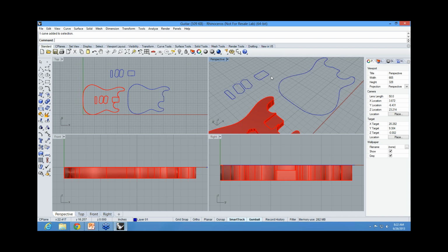And curve Boolean is a great command to, as soon as you make the curves for the TrueType, go through it with curve Boolean, pick inside every letter, and it will clean up the overlaps. It'll clean up the small little loops. It'll clean up that geometry, and you will find that it will work much better for 3D modeling further down the road. And so we use it for finding outlines. We use curve Booleans for inlays, and we use curve Booleans to fix font curves quite a bit. So those are some areas that we use curve Boolean.